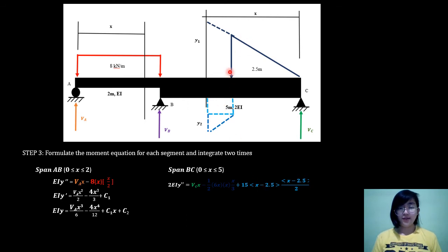So, x over 3 kasi 1 over 3 times yung distance. Plus, since nagdagdag tayo dito, meron pa rin tayong force na nasa baba. So, it's a trapezoidal load. Pwede natin siyang gawing square or rectangle and triangle. Paghihiwalayin na lang natin siya.